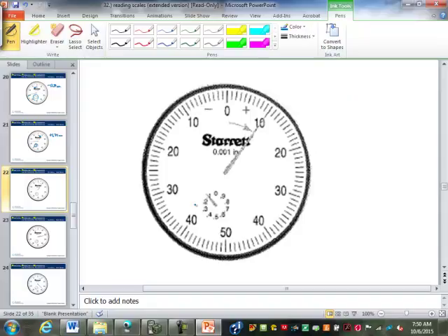So this one, do you see a change here? You'll see decimal points down here would be the first indicator instead of just whole numbers. You look closely, you see this is 0.001. This is now an inch indicator. So what we get down here is not whole millimeters. This is tenths of an inch. So it's a positive 0.1. Yeah, that's at 10, so 110 inches. It's 110 thousandths.